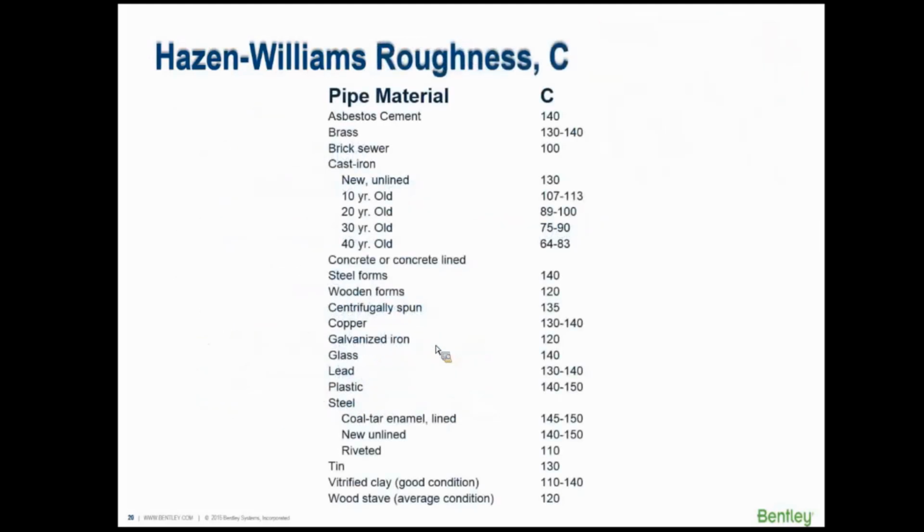And so generally you'll look up some tables like this of different types of pipe when new and at various ages of the piping. And we have a whole bunch of tables like this in our textbook for different values of C-factor because they don't change too much in the short term and they don't vary with velocity very much. There is some variation, but not too much.